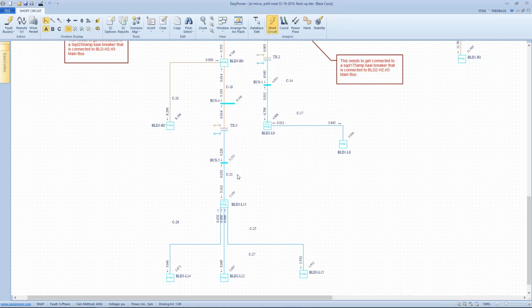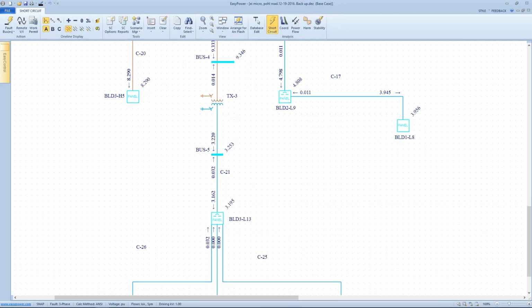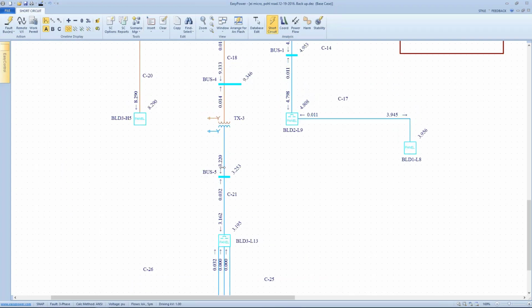And so what we see here in this system, in my 208 volt line, I've got a maximum of 3,200 amps during the first half cycle. And in this system up here from a larger transformer, I got a maximum of 4,798. So these numbers are borderline as far as some of those reports that we were looking at, borderline being in the range of self-extinguishing when it comes to an arc flash at that voltage.